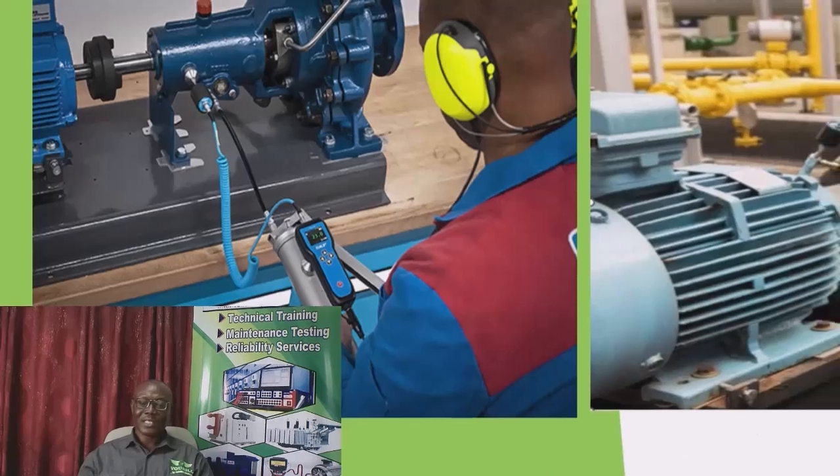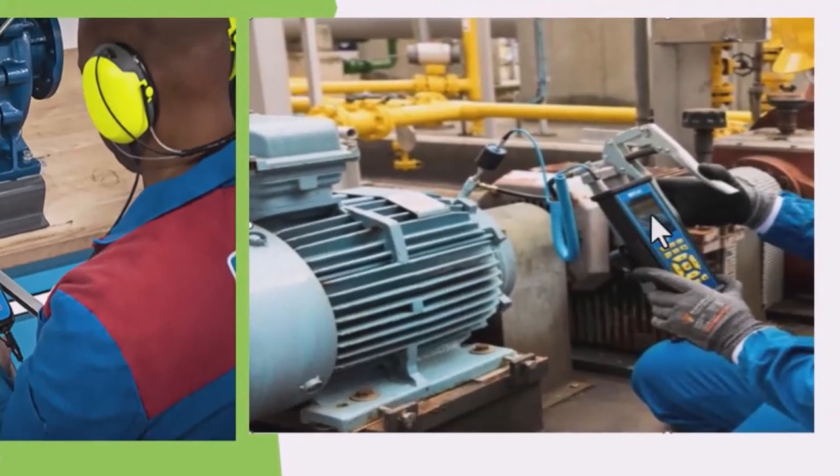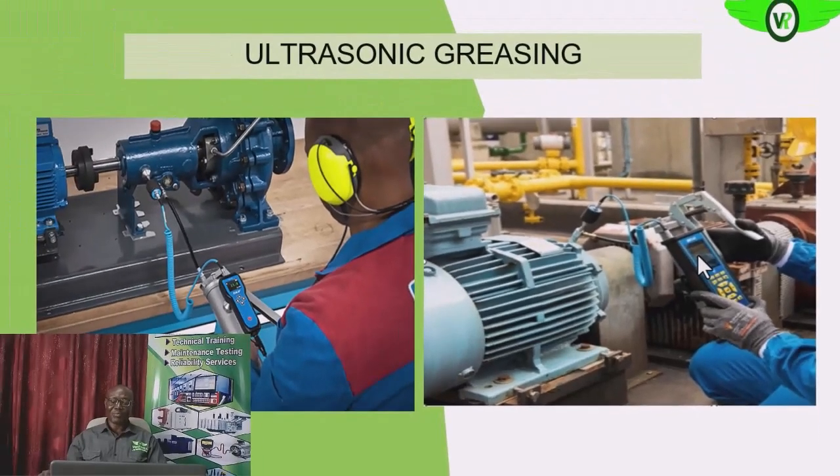Are we getting it? Then on the right, he is viewing the waveform, which is actually more reliable, as we'll see later. When the waveform drops to a lower level, then you know that is the right time to stop greasing the electric motor.